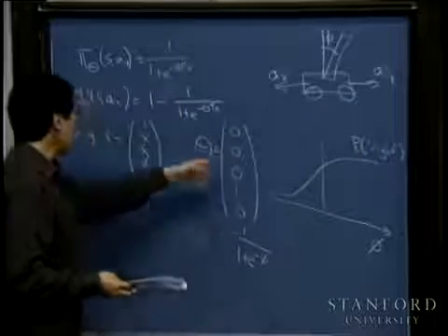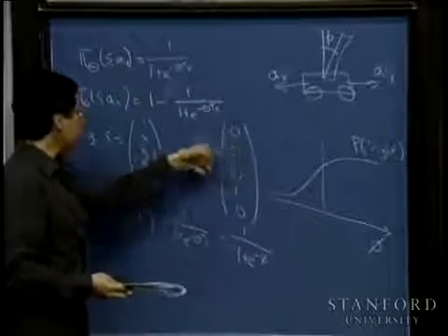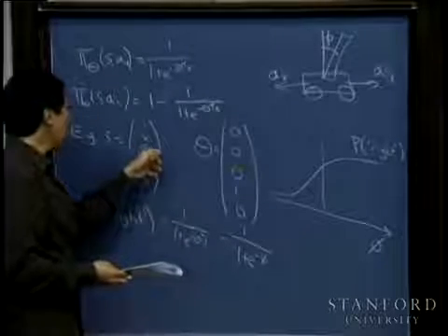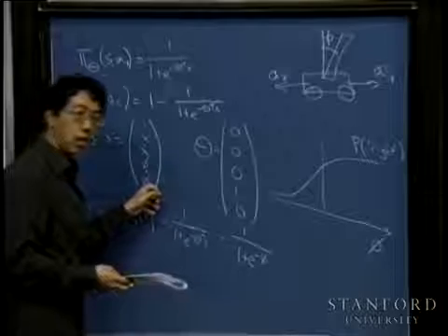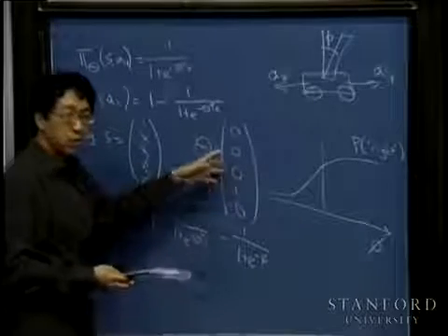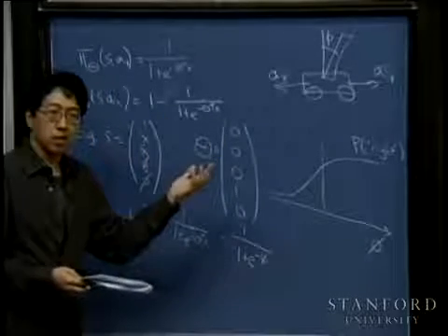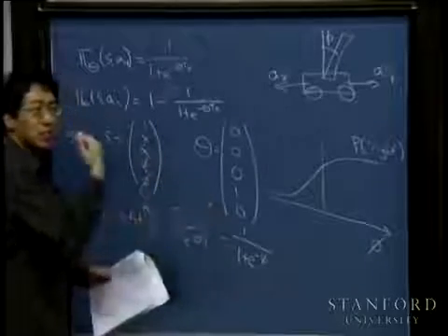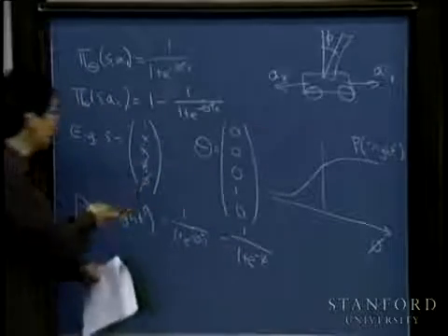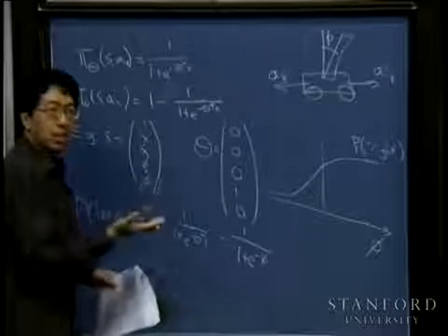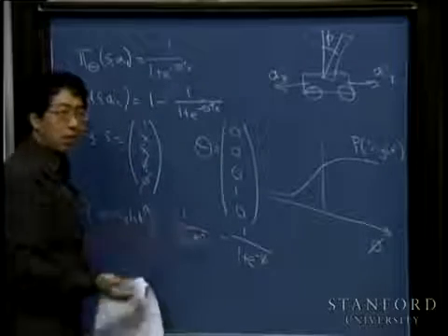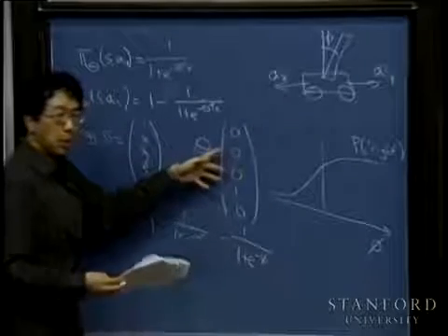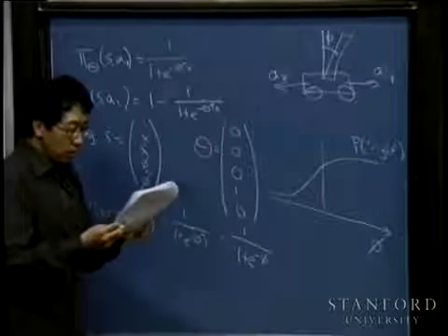And you can capture that by changing one of these coefficients to take into account the actual position of the cart, and then depending on the velocity of the cart and the angular velocity, you might want to change theta to take into account these other effects as well. Maybe if the pole's leaning far to the right, but is actually on its way to swinging back, as specified by the angular velocity, then you might be less worried about having to accelerate hard to the right and so on. And so these are the sorts of behavior you can get by varying the parameters theta.